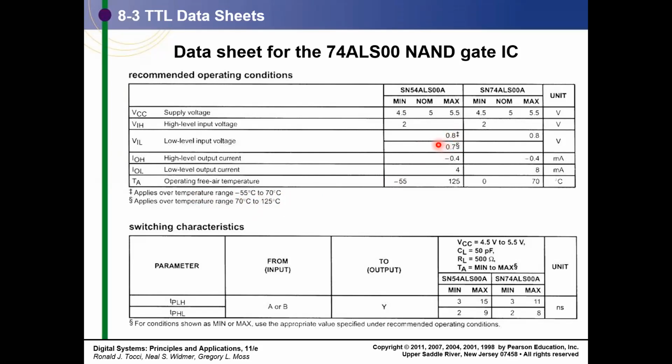So noise margin will cut down at high temperature. You need to specially take care of this for industrial applications. If you are doing a chip in an industry where your temperature can rise beyond 70 degrees centigrade, then we have to design our circuit taking 0.7 into consideration.